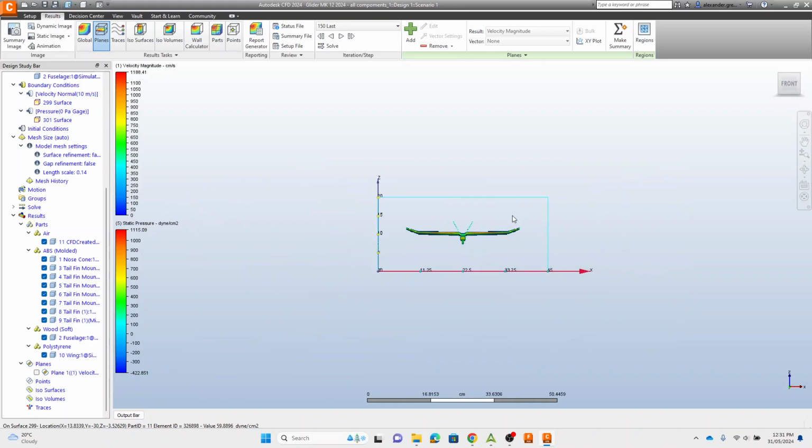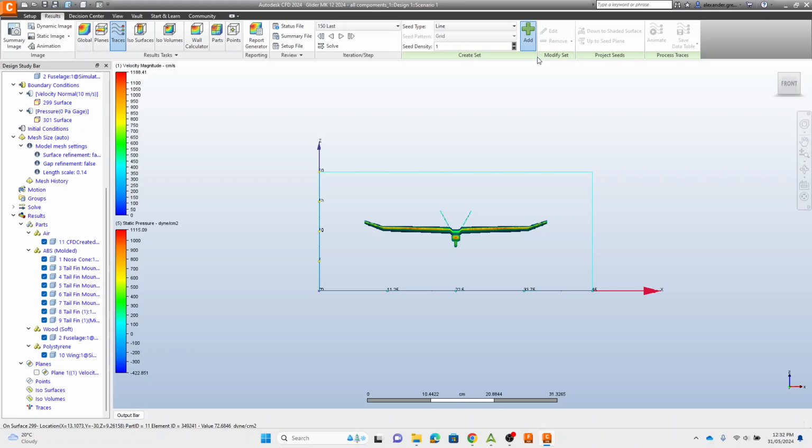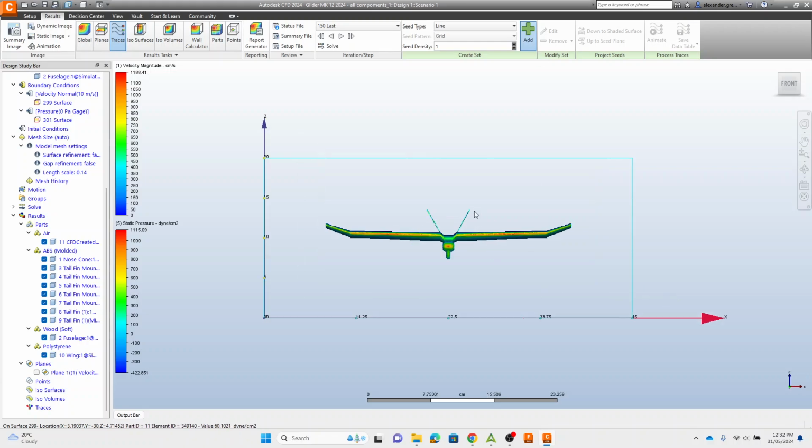the next tool that we can use called traces, and traces is just up here. So I'm going to go to traces, and I'm going to go over here. What I find works really well is just adding little lines of traces. So here, line, I'll go add, and I usually go from the middle out, so I'll click once. I'm not dragging, I'm just moving my mouse down, and I'm clicking again when I'm happy. Okay, I'll go add again, and click another one down as well.